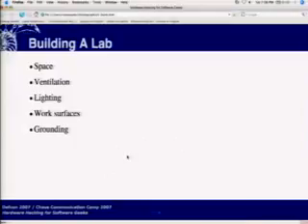Well, in addition to the space, it's also very important how you set up the space. So if you have a table like this one here, you're not going to want to put any electronics on it, because this is a tablecloth. And as I'm sure half of you in here have heard of ESD, electrostatic discharge. You won't know if ESD has damaged your device unless you hit the lottery, and basically it makes it not work at all. And most ESD damage to any sort of circuitry you're not going to know about for months. And then just one feature, or it might be cascading failures down the line. But it can be the cause of a lot of things not working. And it's nice to have that control, so you know it's not your equipment, it's your software or whatever. So you know that you've reduced a number of variables from getting a hack working.